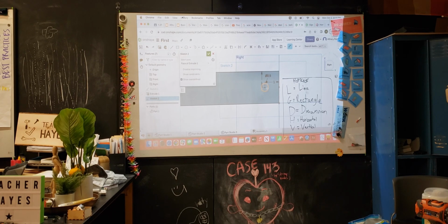So, everybody here, y'all made the T-plates, right? And you all made multiple holes, you have to dimension them all. It was pretty tedious, you have to click dimension, you have to type in the numbers multiple times. So, I'm gonna show you a tool that can quicken all that. Right here, if you go up here, you can see this thing called linear pattern. Click on that. And then you can click on the objects you want to apply it to, and boom.